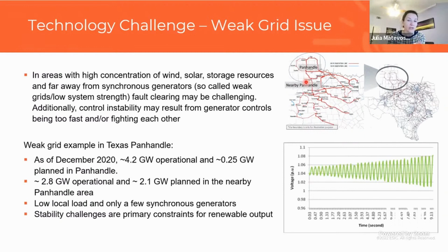It varies. I mean, the good thing is that it's not constrained all the time to just one megawatt amount. They reevaluate based on system configuration at any given time. So that allows some flexibility. They have installed 2 synchronous condensers in the area. So as I mentioned, synchronous condenser is like a synchronous generator without prime mover, and it provides same system strength advantages as a synchronous generator does. So they installed 2 of those in Panhandle area to address weak grid issues, and that allows to increase megawatt amount that is produced from inverter-based resources here.